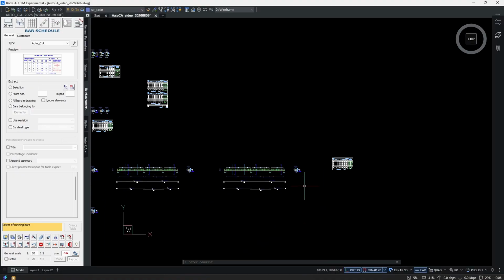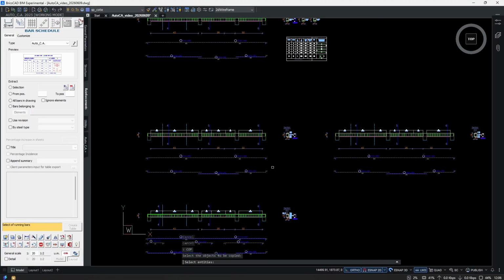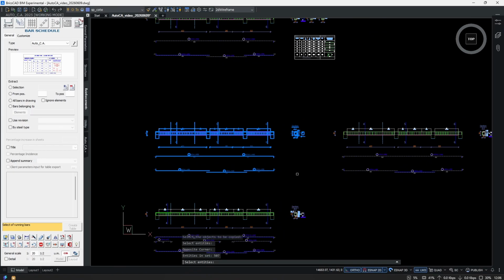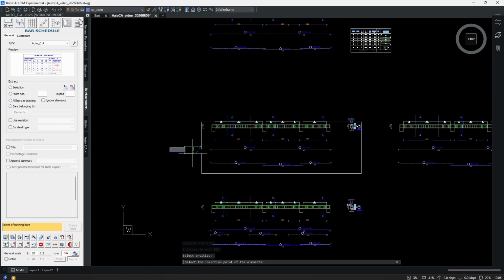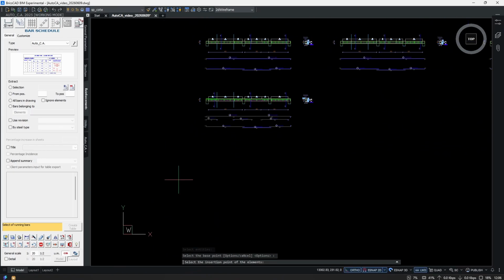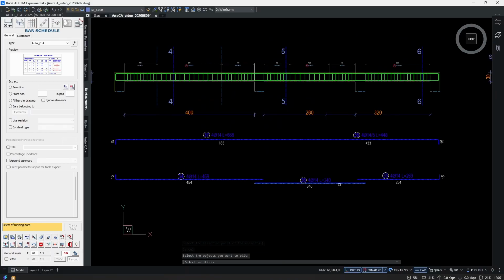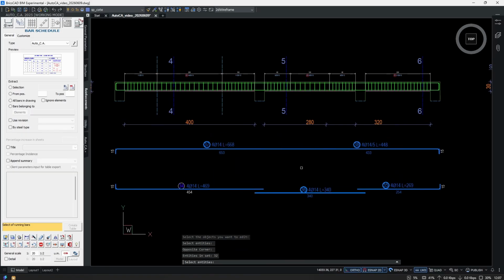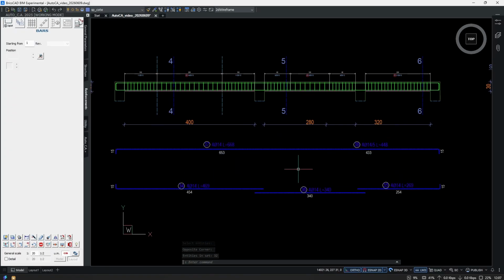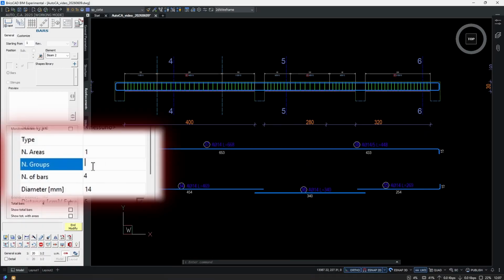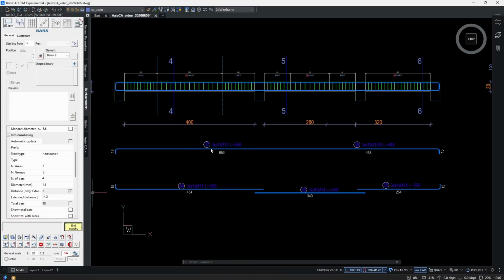And there's another way to do the same thing, which is maybe the easiest way: select one beam of which you have multiple ones, and enter the modification panel first for the longitudinal bar, and here in the group numbers just type in the number of how many beams you have of the same dimension. So for example, I type in 3.